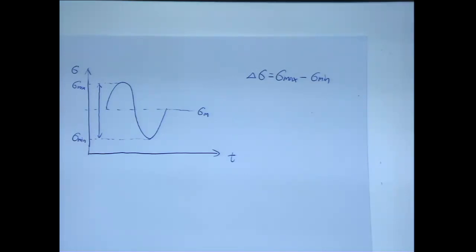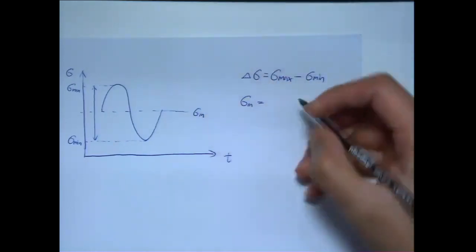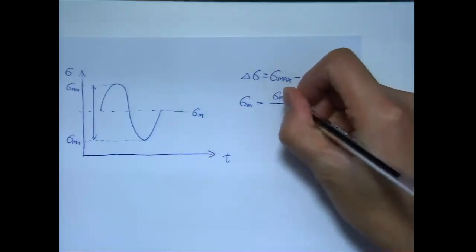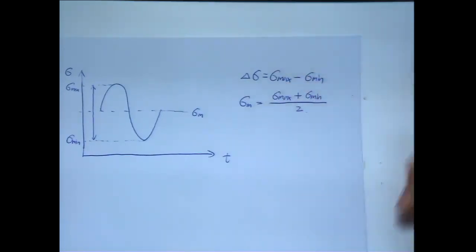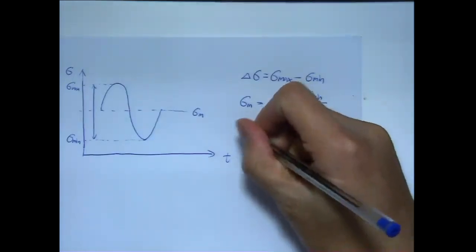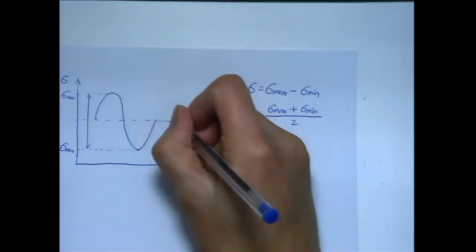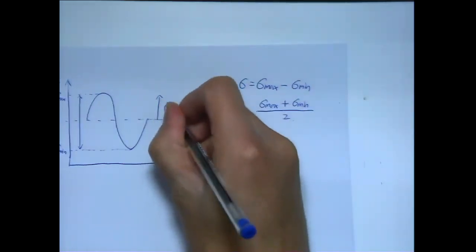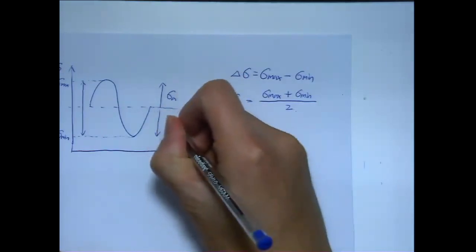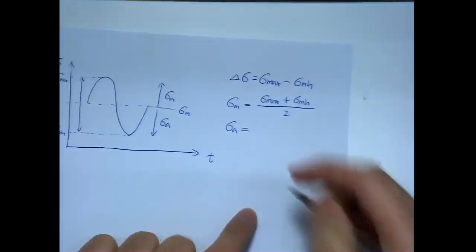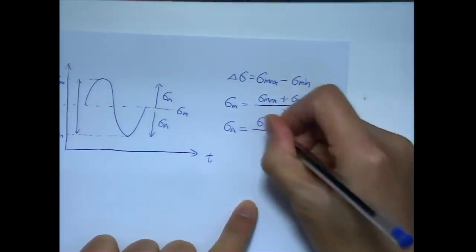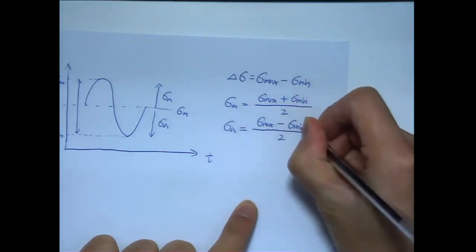So let's say stress variables, including, first of all, the stress range. What else? There is the mean, which is the sigma mean I drew here. It's half of the maximum stress plus minimum stress. Okay? And then there's an amplitude, which is sigma a. So amplitude basically is just from the mean to your maximum, or from the mean to your minimum. So that is half of sigma max minus sigma min. Okay?